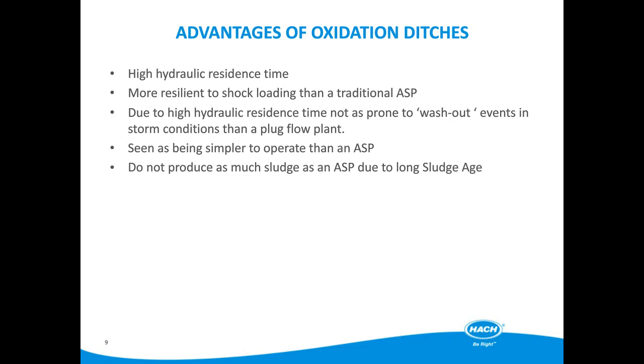The advantages of oxidation ditches are they are considered to be simple to operate. With their long hydraulic residence times, they are resistant to both shock loads and washout incidents due to the volume of the mixed liquor contained within the ditch that dilutes any shock load or toxic event. Control is usually only by dissolved oxygen.